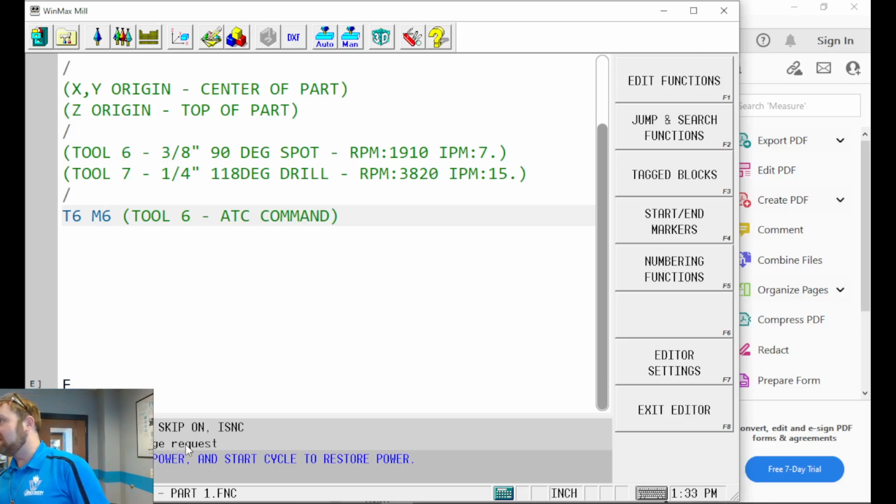When I set up a machine, like on a FANUC control, when I'm trying to switch through tools, I'm going into the MDI page because it's the quickest way for me. I type in T, whatever tool I want, M6, tell it to run that, and it brings that tool to the spindle for me. That's literally just writing a short little line of code telling it I want this tool in the spindle.